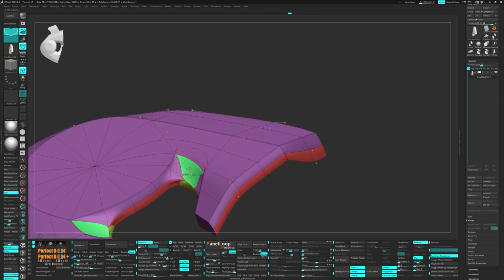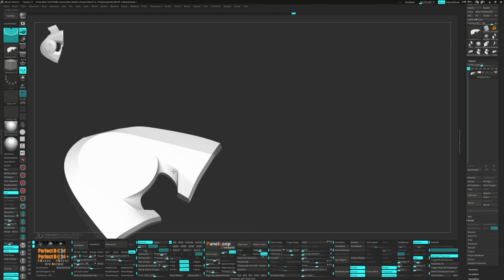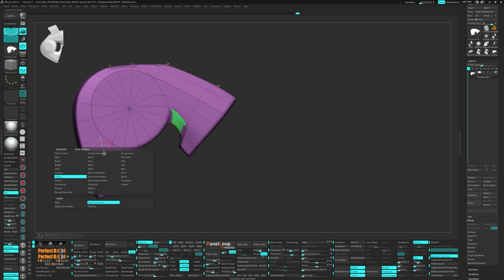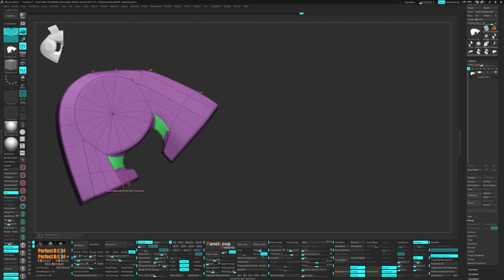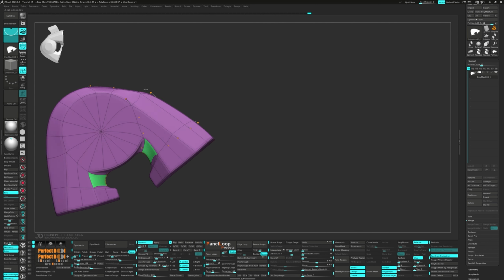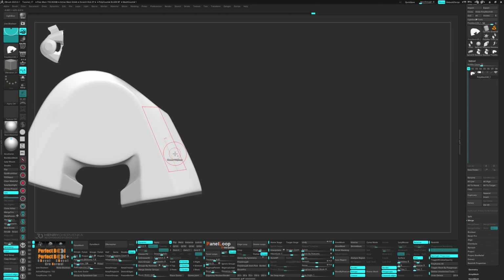Another trick up your sleeve could be to load one of the Shadowbox projects found in Lightbox. But remember, doing so will clear out all the custom objects in your tool palette, so it's like starting with a clean slate. So all in all, Shadowbox is pretty awesome for hard surface modeling. It's quick, straightforward, and it can handle complex shapes, making it a tool worth getting familiar with.